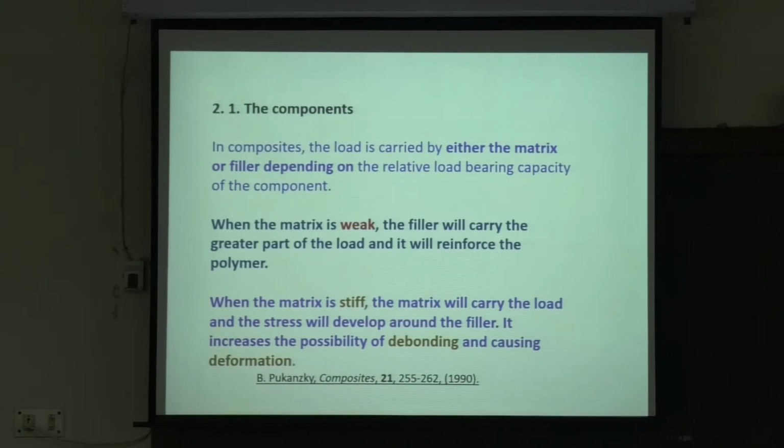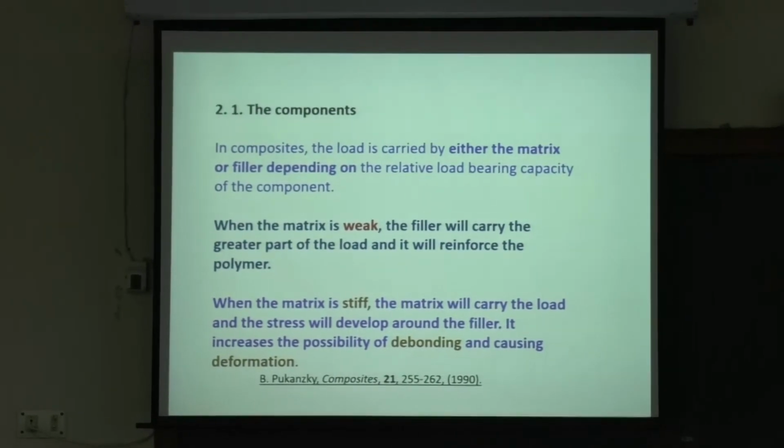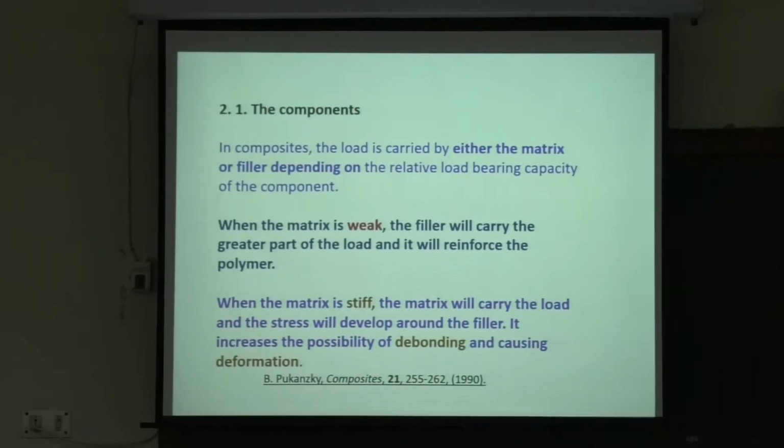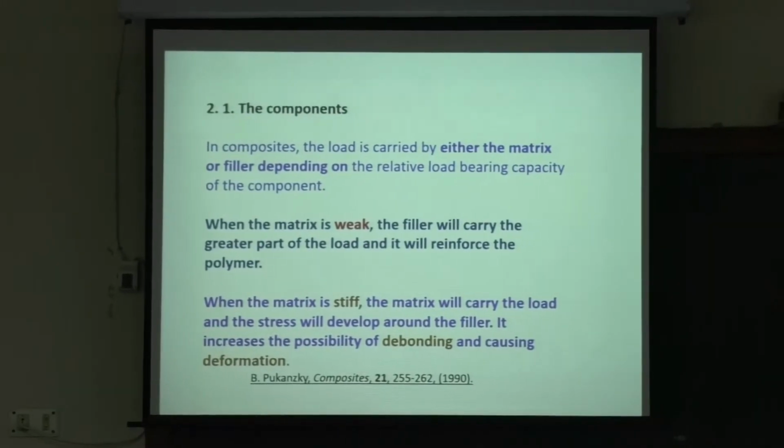Even if it breaks, if the reinforcement is there, the crack is going, and the reinforcement will stop the crack. Then for the crack to propagate, it has to either crack this particle or the fiber, or it has to go up like that and do other things. But that's the secondary thing, all right? When the matrix is weak, the filler will carry the greater part of the load and it will reinforce the polymer. But when the matrix is stiff, like if you are having steel, and then you are putting